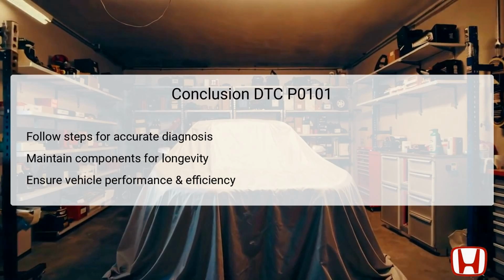In conclusion, troubleshooting the DTC P0101 error involves a systematic approach to identifying and resolving issues with the MAF sensor circuit. Following the detailed steps, starting with visual inspections and progressing to more complex diagnostics, ensures thorough investigation and correction of the underlying problem.